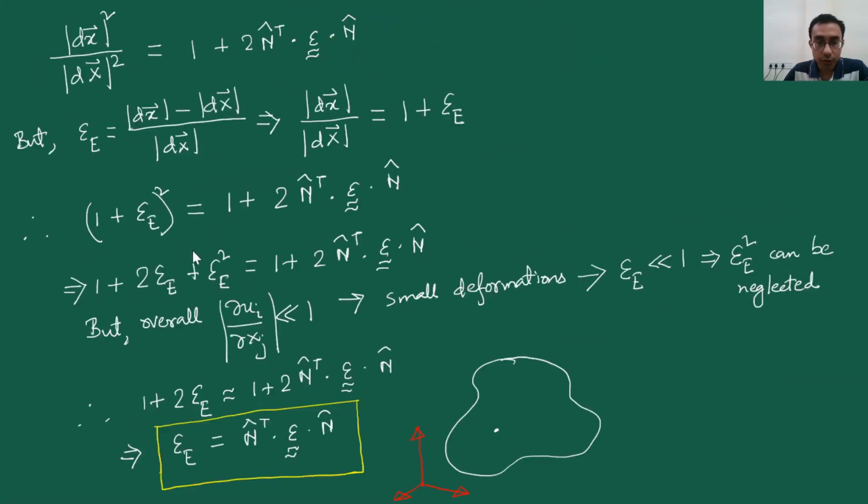So if we come back to this picture, the picture that you have in your hand is this. You are sitting at this point, and at this point you know the various values of the strain components. Which means that in this entire formula, you know the 6 independent components of the epsilon. Next, you ask the designer or your customer in which direction they are interested in finding the engineering strain.